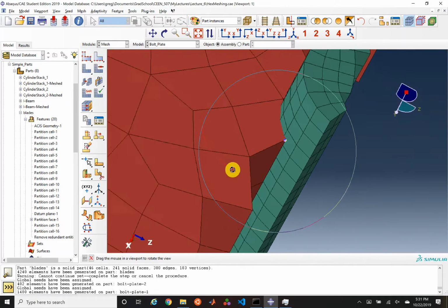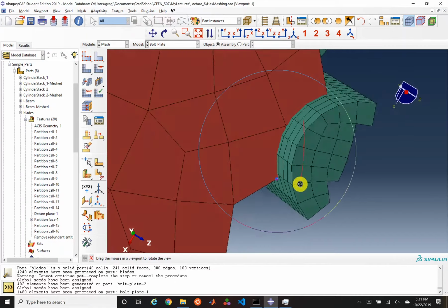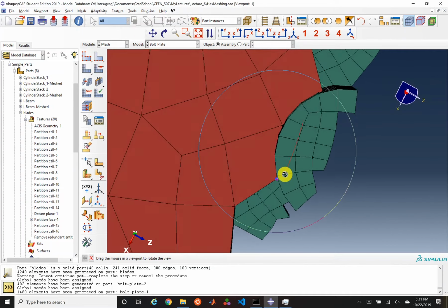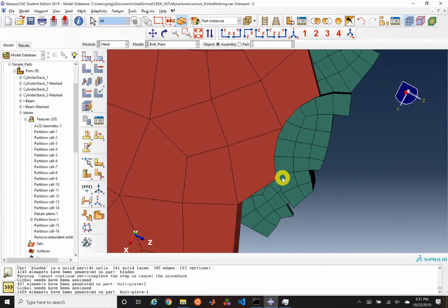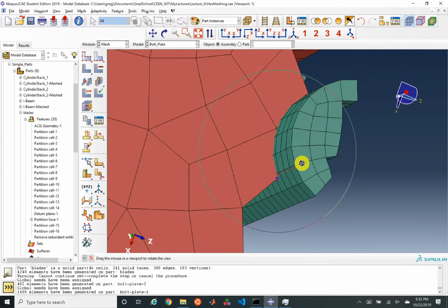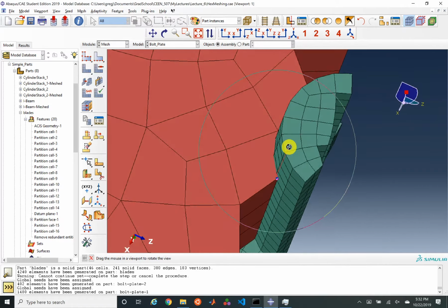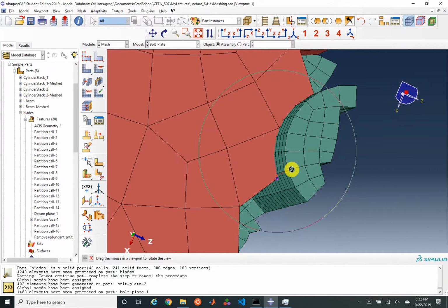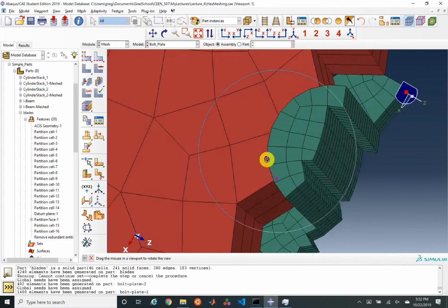This is part of what we're going to talk about in class about isogeometric analysis. If you're defining your geometry with smooth splines, or non-uniform rational B-splines in the case of the circles, but then you're transforming your geometry into linear facets, you're no longer going to have perfect mating between parts in many cases.